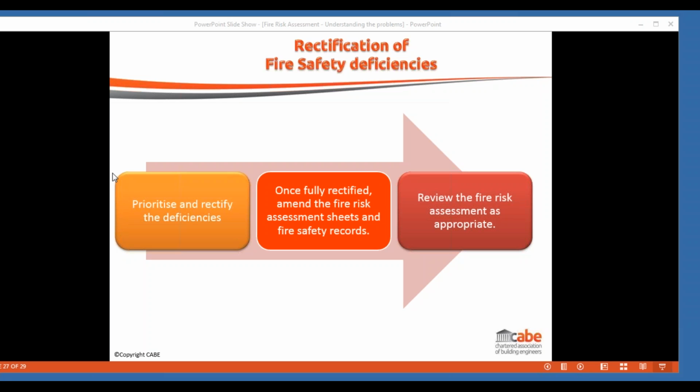Okay, next question. If travel distances are exceeded in a care home, if only by a metre or so, should additional fire doors be recommended, or could alternatives be considered such as smoke detectors, fire suppression, etc.? Residential care is always very difficult because obviously there's a degree of residential care where the people within the premises are going to need assistance to get out. Evacuation in a fire, should a fire get to that stage, is going to take longer, is going to be more intensive in terms of staff assisting people. Training is going to be critical.